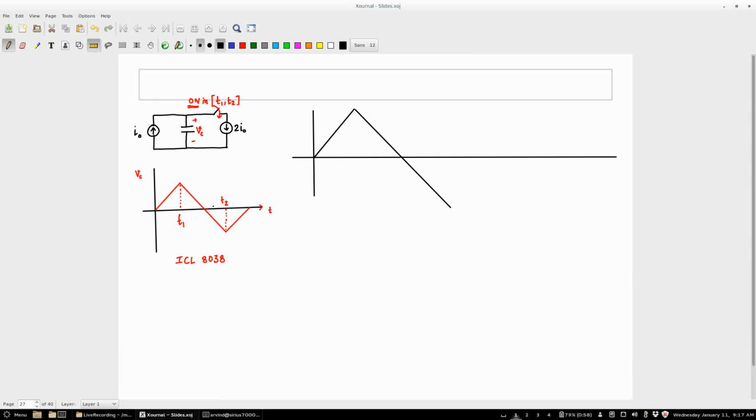We just pass it through a comparator, right? If you pass it through a comparator, will that work? No, think about it. You will get a different period. If I pass it directly through a comparator, then wherever it is positive, the output becomes positive, and wherever negative, it becomes negative. That's the easiest way to convert this to a square. So comparators are also something that can be used.